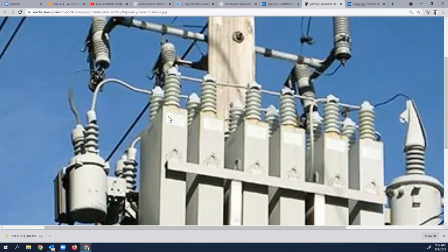All right, so I've got a 400 cell that's paralleling. I now have an 800 kVAR capability right there. You have to parallel the cells in order to get 800 kVAR out of 2 400 kVAR units.